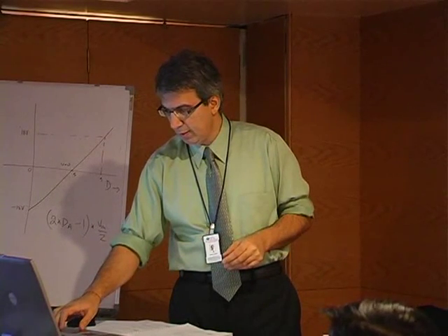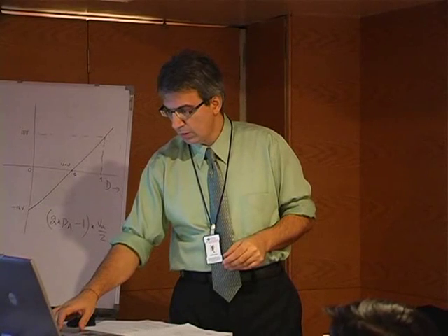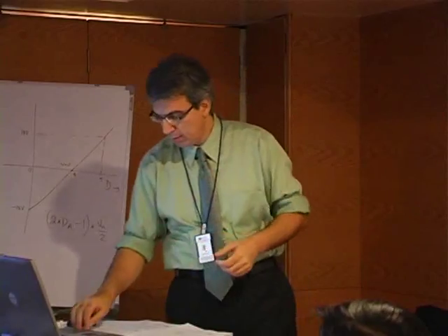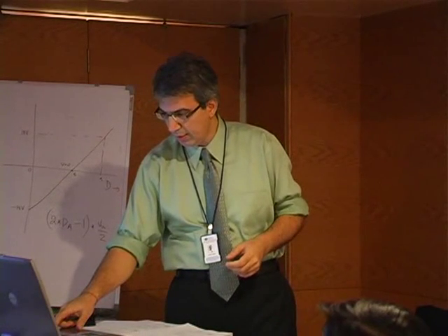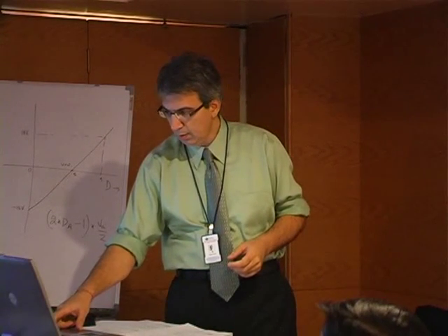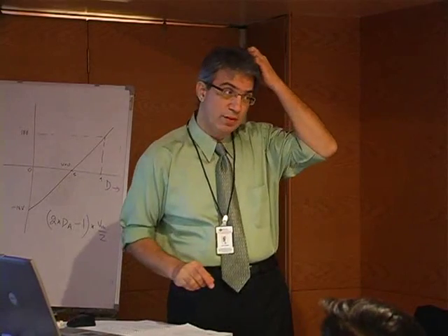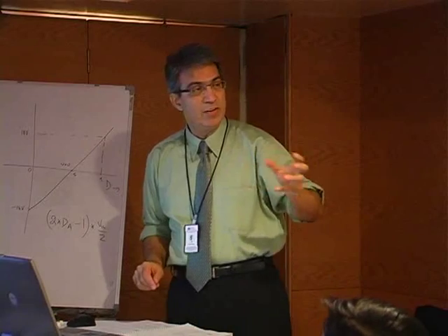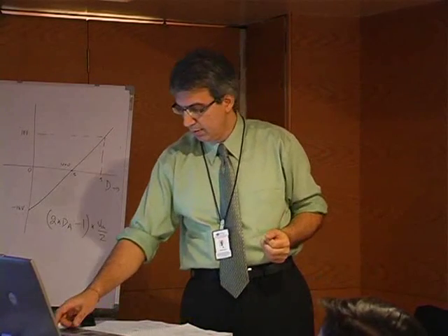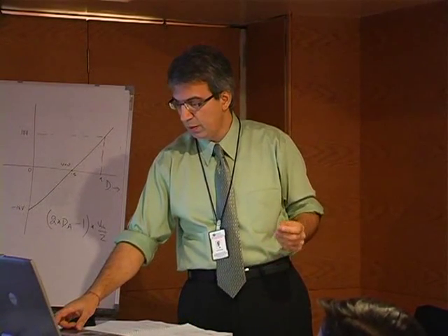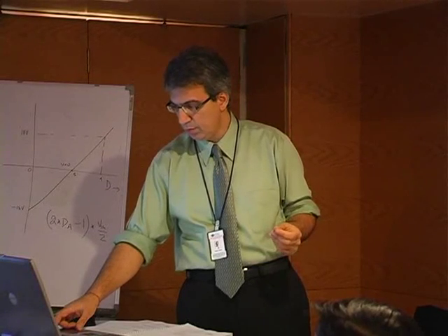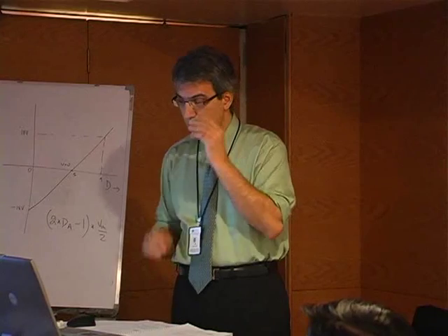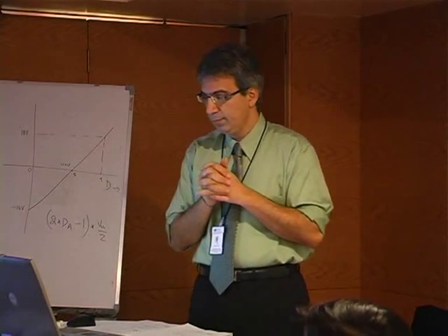All right, I think this is an example. We will not run this demonstration since we are running behind schedule, but to give you an idea here, you have a low frequency, 10 hertz, and then your MF is 20.5. Here still MF is not large enough, and consequently your PWM frequency is very low, 205 hertz, and so you begin to see subharmonics in your plot.